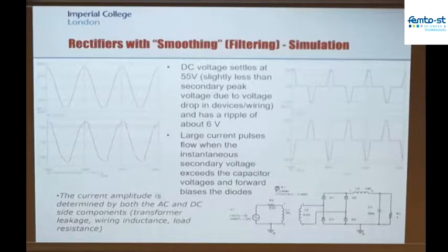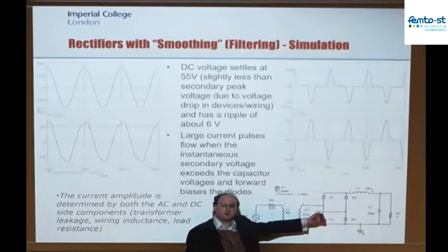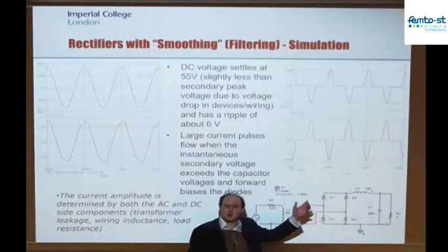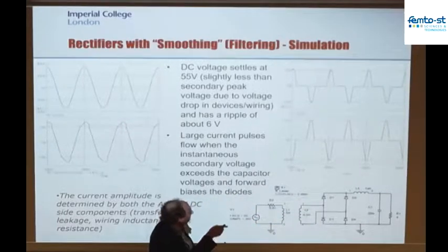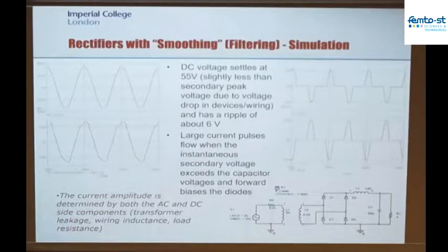Well, I can't do that with this circuit because now it pulls a current from the harvester only at the peak of the waveform. So I've lost that nice linear relationship, and I've got just peaks of current that are flowing. So that's probably not very good in terms of operating the harvester in the nice linear mode that I was expecting.